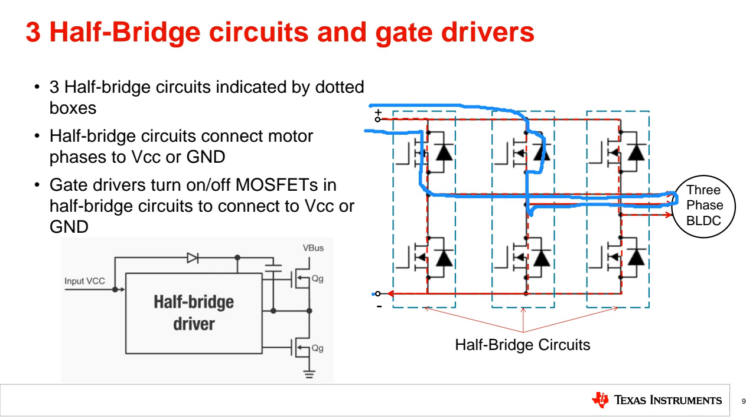Gate drivers will be seen in the reference design. For example, you can search Google for a BLDC motor driver design reference manual. You will see which type of half-bridge driver or discrete gate driver is used in the BLDC motor. In motor control, don't forget, you always start with the reference design. I will show you lots of reference designs in the next weeks. Lots of topologies are available.